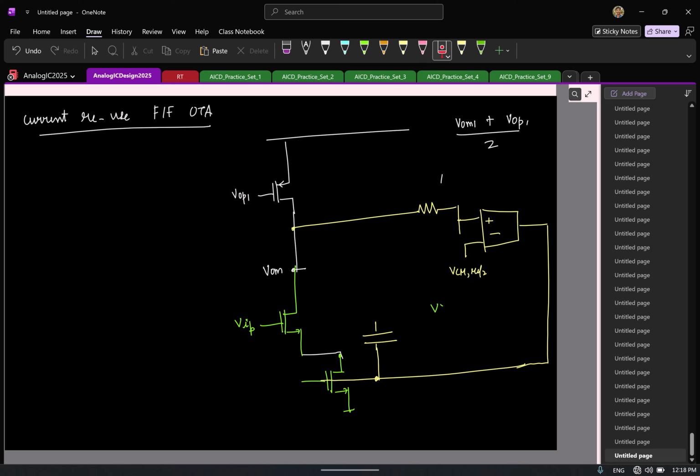I mean, should I connect it here, here, or here? Lower, middle, upper. Which one? Middle? Why? Remember, across the second stage is where you are supposed to put the capacitor. The input to the second stage is here, whereas the final output is here. So you basically go and put the capacitor.